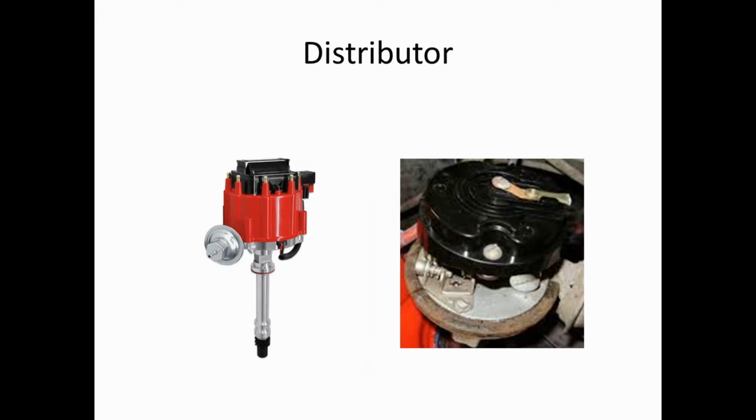And so this is the distributor cap. It's an essential part of this. It has all the different terminals in it. It's what allows the spark plug wires to be put on at different points, just for your engine firing order. And our rotor distributes the spark to all the different terminals inside the distributor cap.